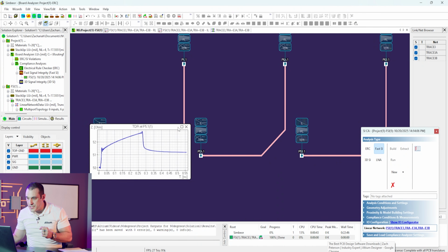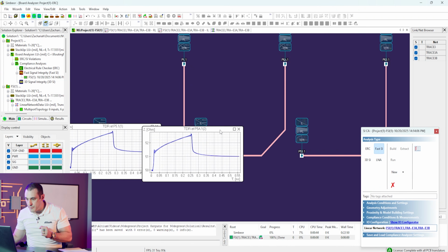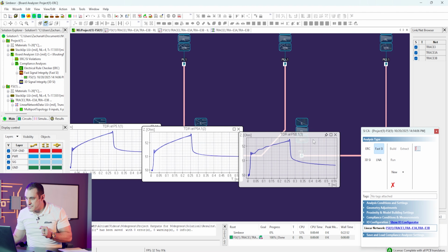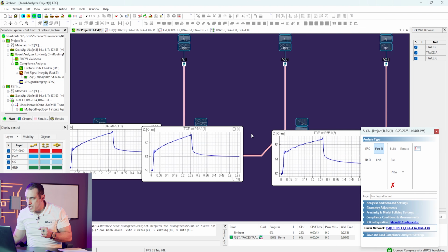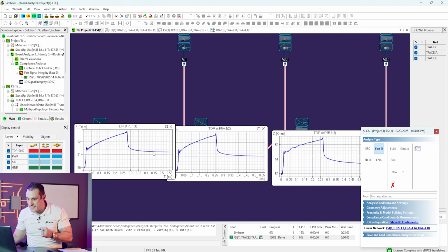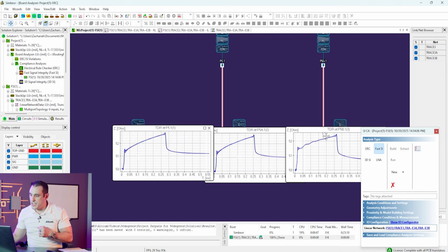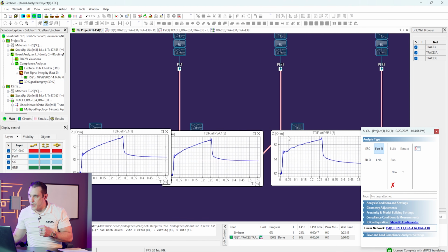I'm going to go ahead and bring these up and pin them. So you can see here that when we bring these up, we actually do see a slight difference in the impedance that's encountered along these traces. Eventually, the trace impedance does fall back down closer to the target impedance around 51 ohms when we use the curved trace compared to the 45-degree trace and the right angle trace.